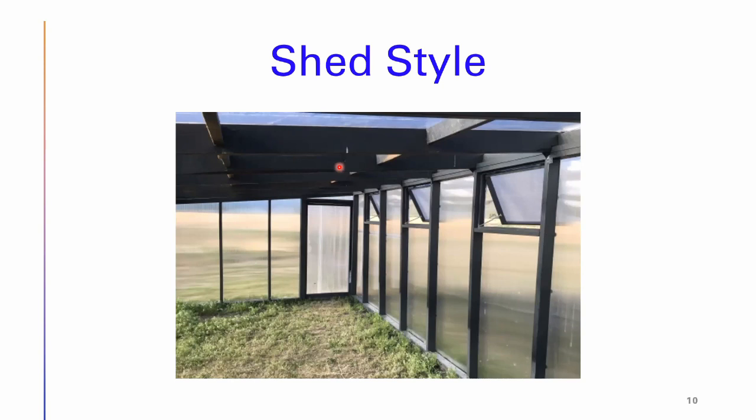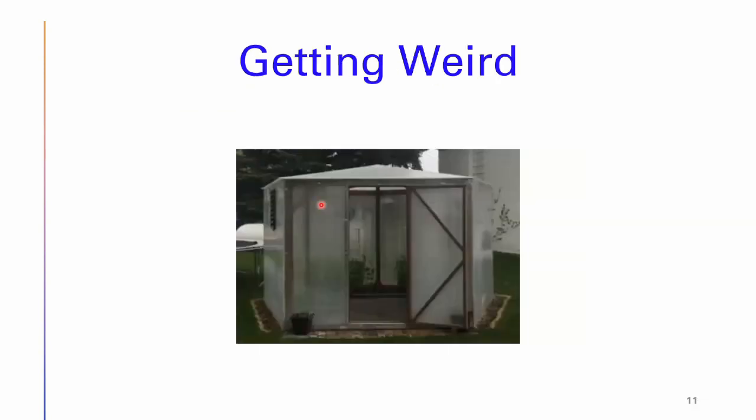But to invoke that, you have to have a heated environment. What I found on greenhouses, even with this crazy narrow 1.5 to 12 pitch roof, is that it slides right off, because the greenhouse warms up enough that it heats the roof, and polycarbonate is smooth enough that the snow slides right off. You don't have to worry about significant accumulations of snow unless in really crazy extreme situations.